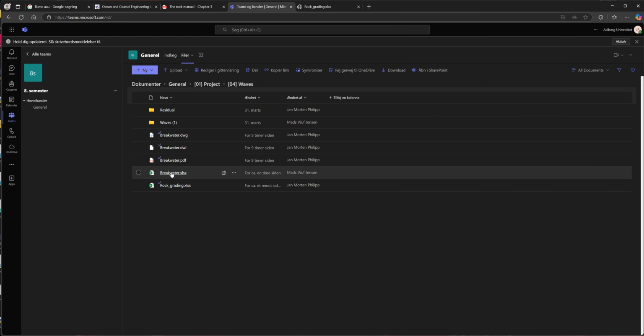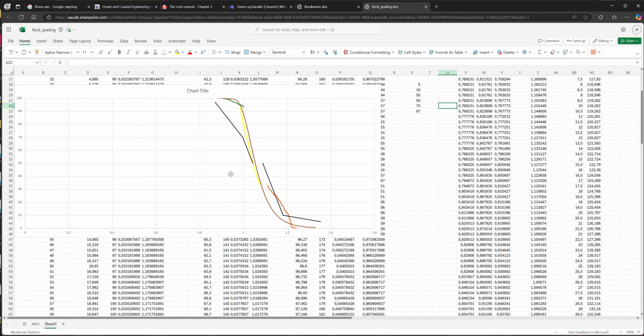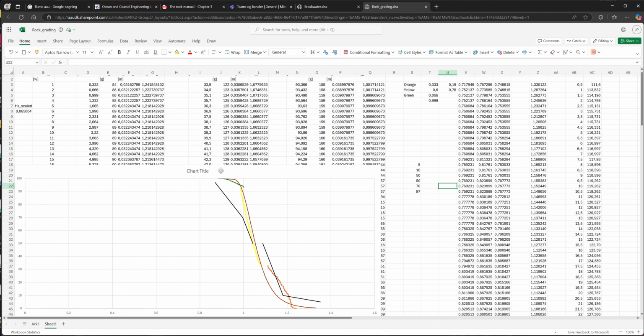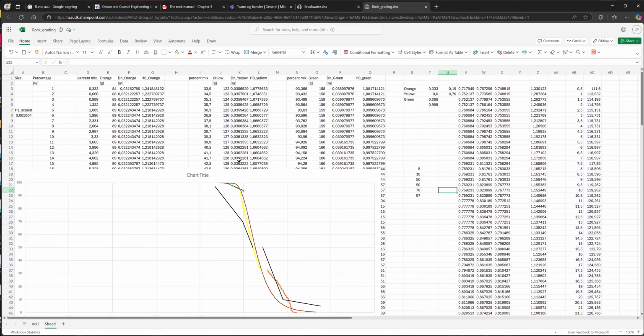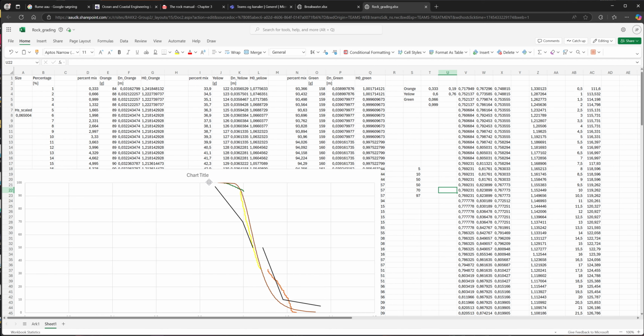As we can see, when we made the breakwater and scaled it, the stone weight that we calculated for our stones was scaled down to 140.29 grams. So the yellow stones are very fitting to that, actually also to the size that we want to see. But it is not realistic that we have such well-fitting stone sizes. So we want to make a blend of some stones.